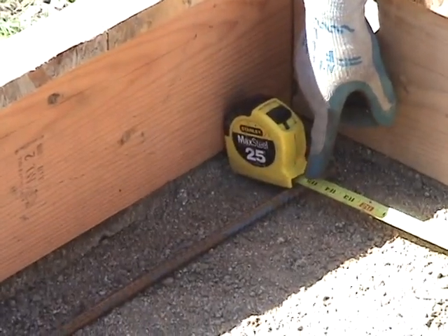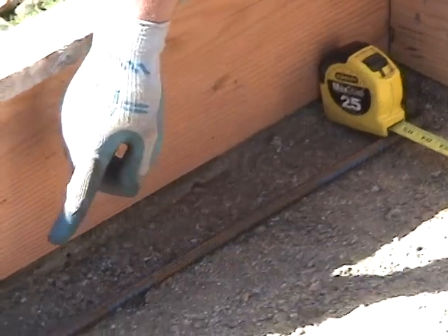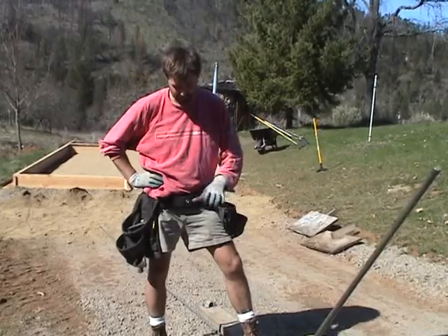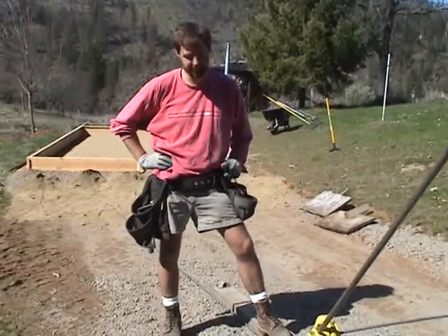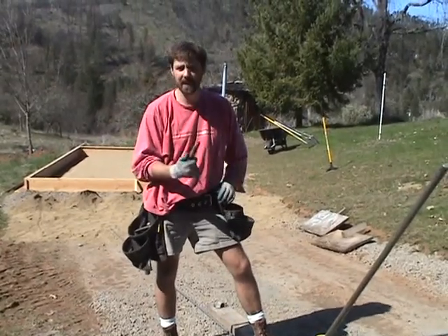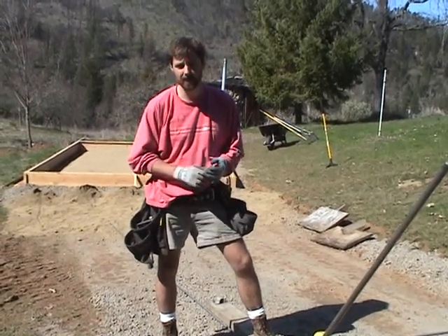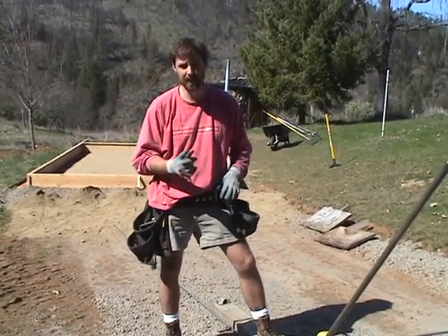Now I'll need to remember to add 2 feet onto that after the bend to connect it to this other piece of rebar that we already have in place. So for marking the rebar when you're measuring lengths, it's good to have a lumber crayon or something that's got a little more meat to it. You're not going to be able to mark on the rebar with a pencil. So this shows up pretty well. It gives you a pretty accurate